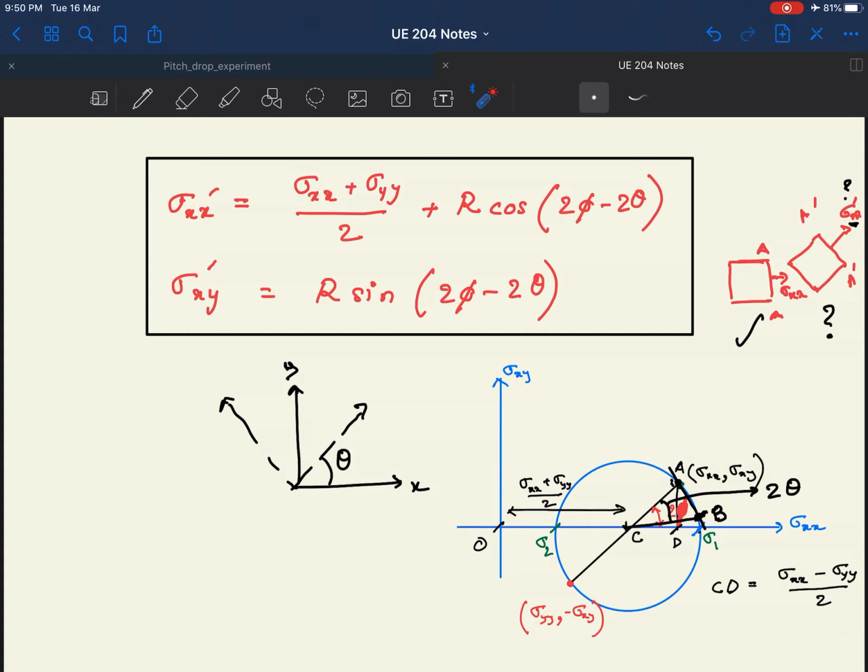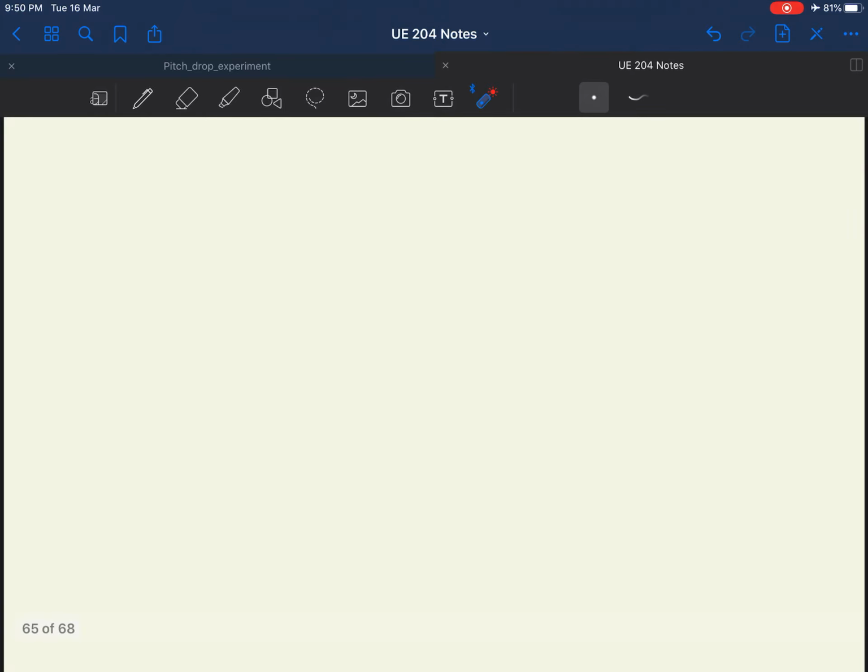So this is one of the ways of making the Mohr circle. And here, interestingly, you have to observe that the directions of the rotations are opposite, right? So here you have a counterclockwise movement, whereas here you have a clockwise movement. There is another method in which the conventions are changed a little bit so as to allow for rotations to sync with each other, and that's one of the things we want to discuss today.